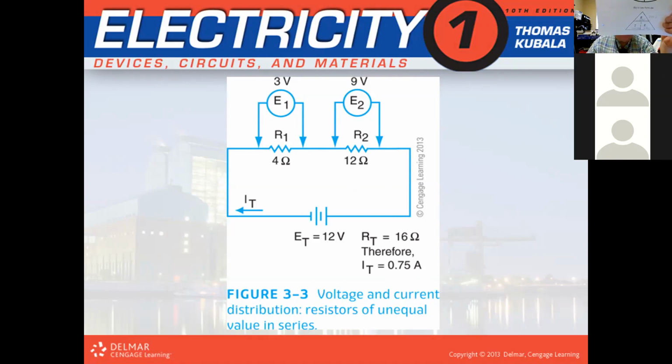So here's how you calculate those different voltage drops: you take the I total, which is the same in the whole circuit for both of these, 0.75 amps, and it's I times R. You take that 0.75 times 4 ohms, and that equals 3 volts. You take the 0.75 amps and multiply it by 12 ohms, and it gives you 9 volts.